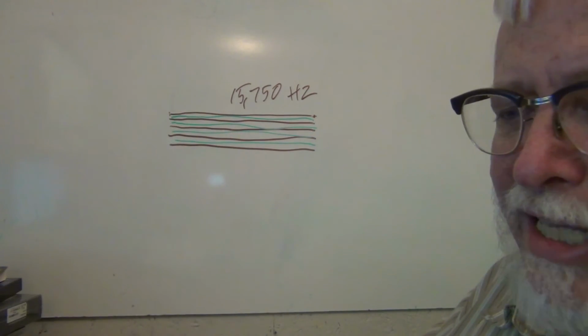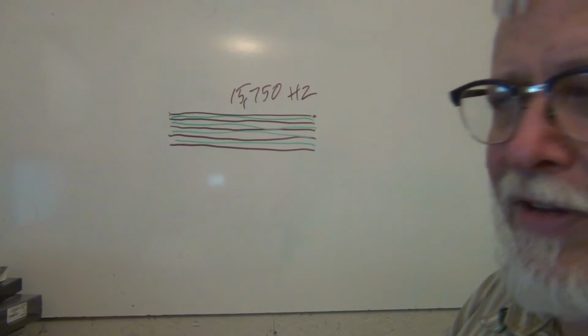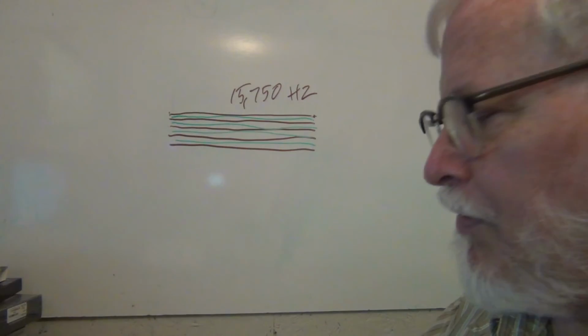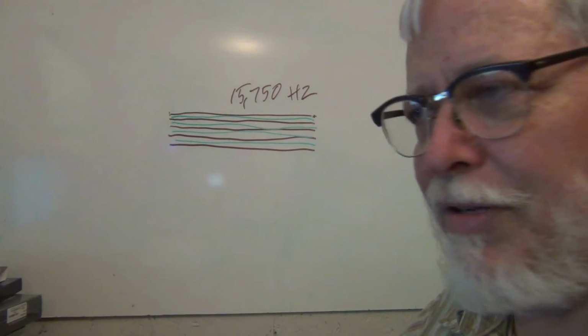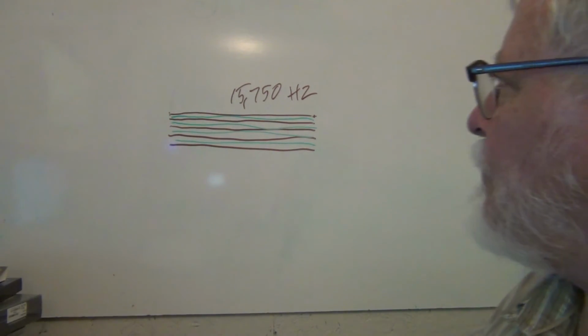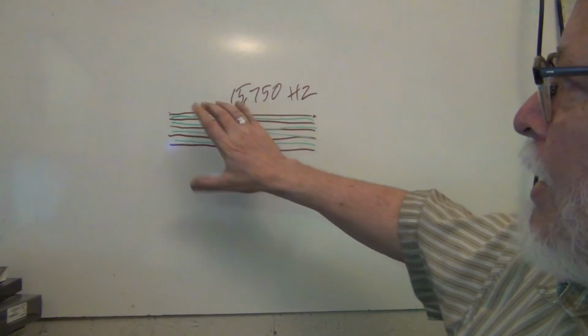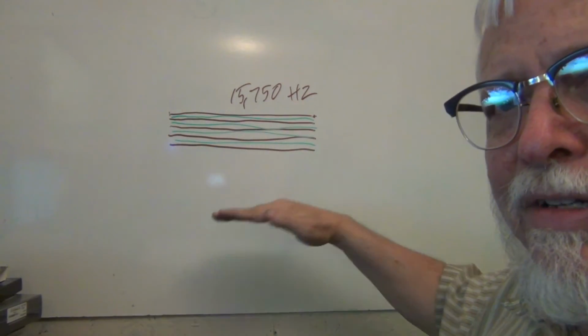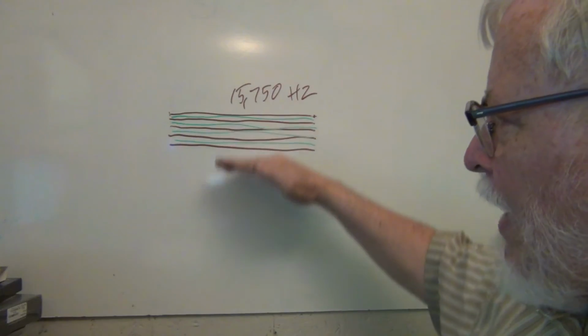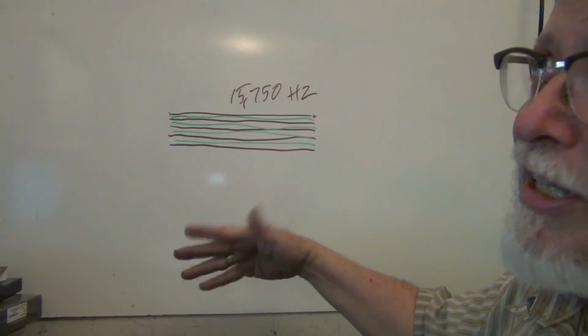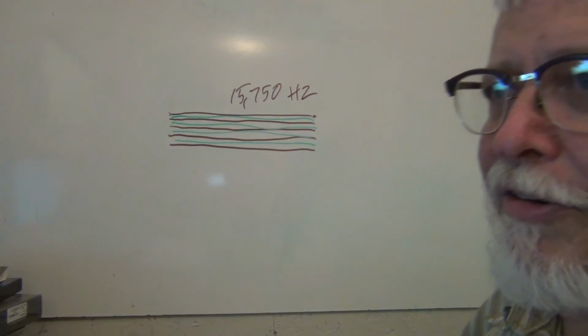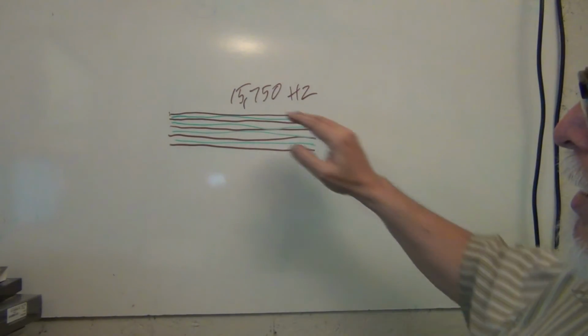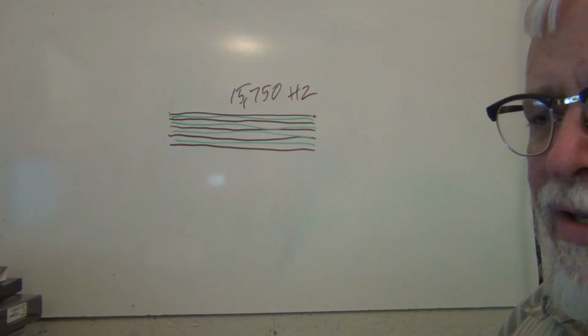With HD TV, that's all out the window, and they've got progressive and interlaced and all these different formats, but we don't need to talk about that just yet. So by the time you have a standard NTSC picture, you've got 525 lines. Actually, there are only 480 something that are visible, and that's called a raster.